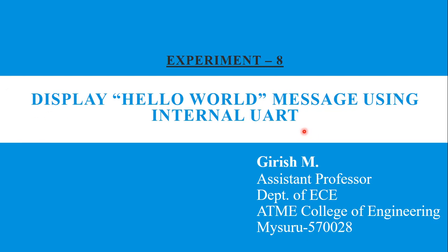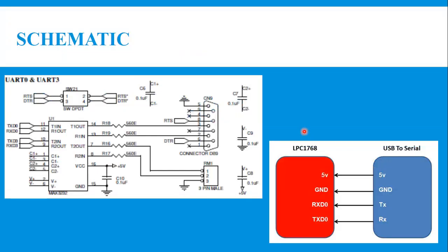The LPC1768 has four inbuilt UARTs, namely UART0 to UART3. Here we'll restrict our explanation to UART0, and similarly you can extend it to the other UARTs. The only difference is the pin numbers you are going to configure, which will vary.